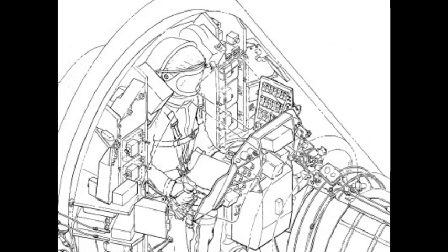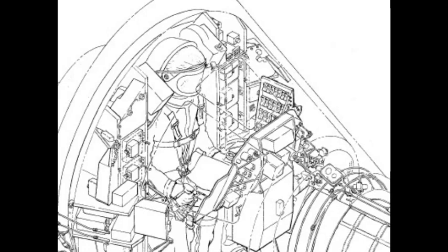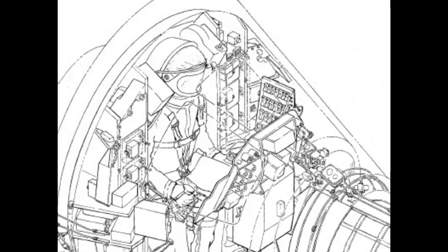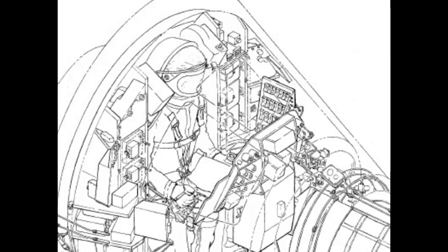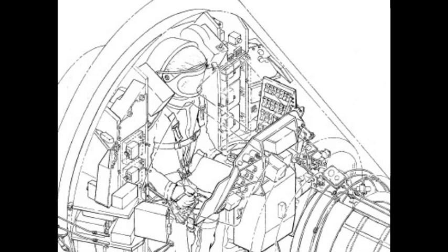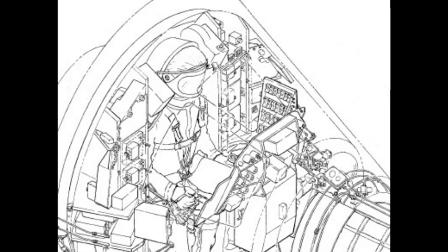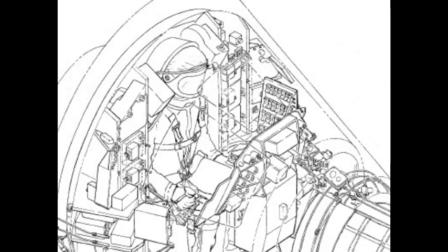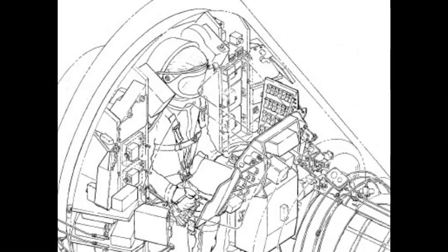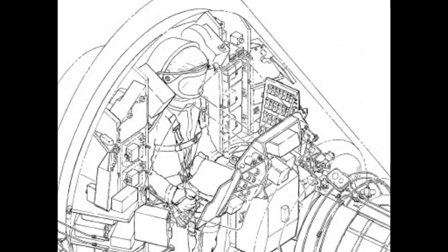The bulkhead inner skin is provided with two vertical channels, centrally located and spaced, that furnish structural attach points for the astronaut support couch. Honeycomb shelves are provided on the bulkhead inner skin, outboard of the two vertical channels, for equipment installation. The bulkhead outer flange ring is bolted to the conical section inner skin, and the bulkhead is also bolted to the conical section inner attach ring. Vents are provided in the large pressure bulkhead to enable outboard venting of the capsule battery vapors and environmental control system exhaust steam.